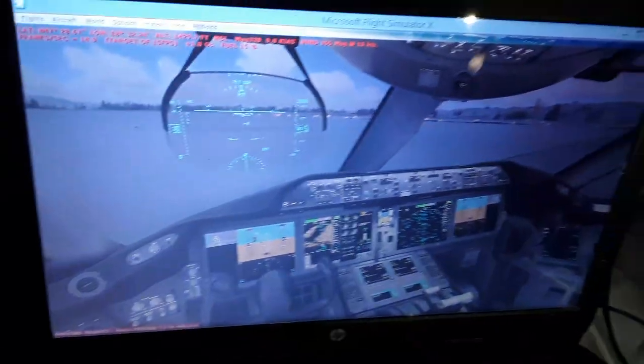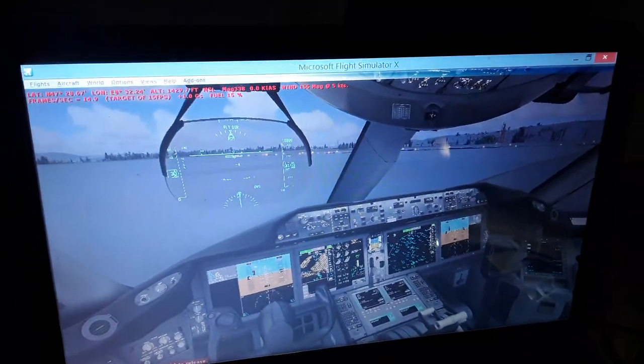Also as we climb higher, the fuel, the oil and the lubricants will freeze. The fuel will freeze at -37 degrees, so it can recirculate the fuel from the left and right wing fuel tanks and the center tank into the engine components to heat up the fuel, also the lubricant and the oil, and this is done automatically by the FADEC. The FADEC also has other functions. We don't have enough time right now, so I'll show you now the flight management computer.